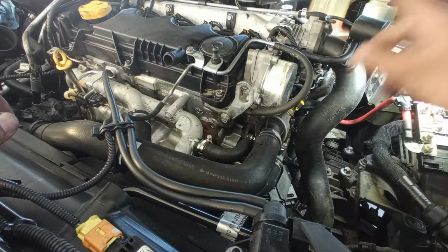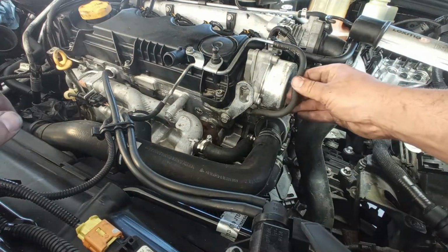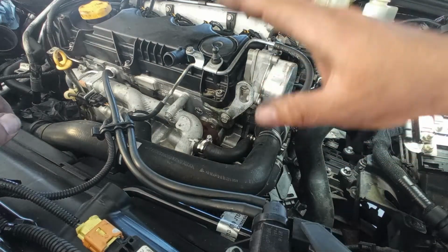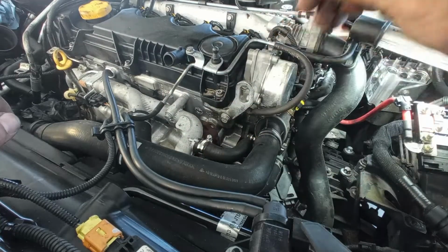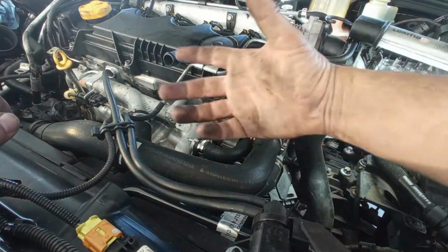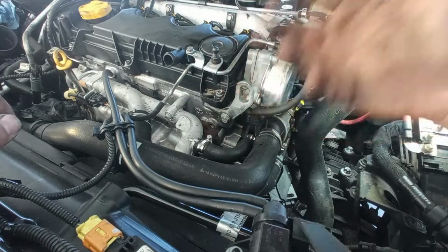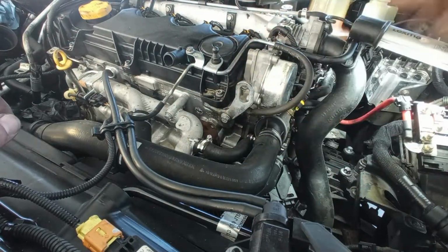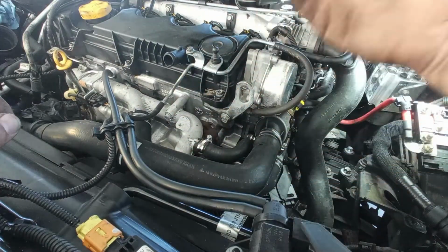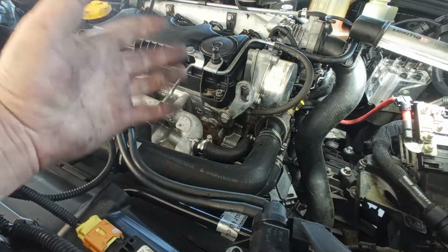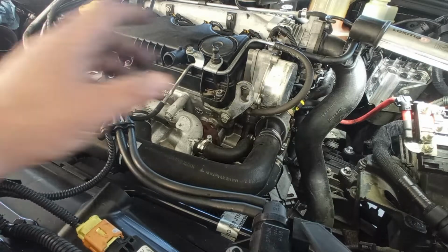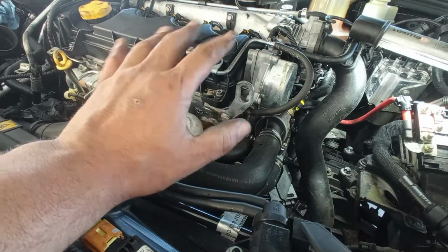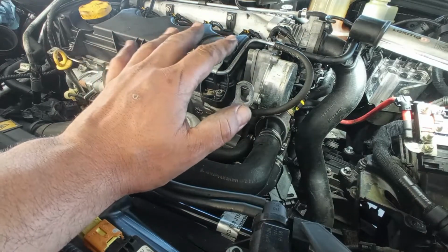I have another car with that problem over here in my workplace, okay? So lack of regulation of the turbo pressures will also affect your air quantity and pressure, and in that way affect the functioning of the entire engine, in that way also of the DPF. Yeah, so for now all the faults that I could find are found.